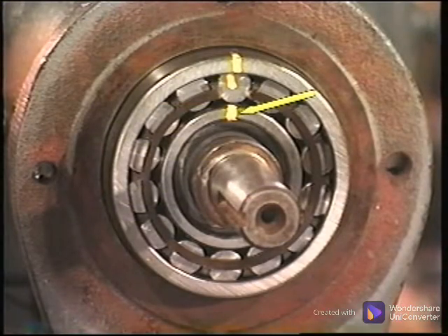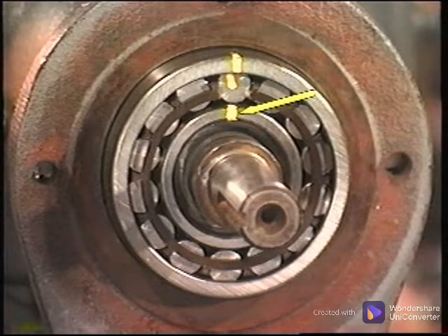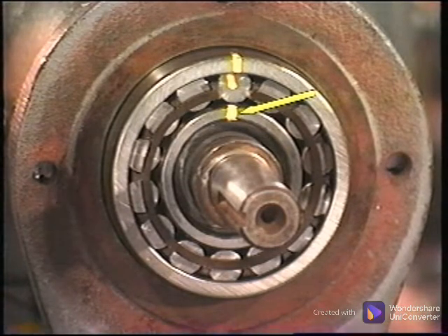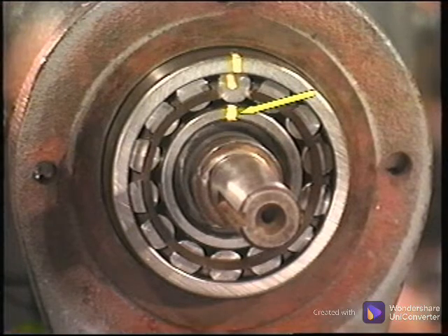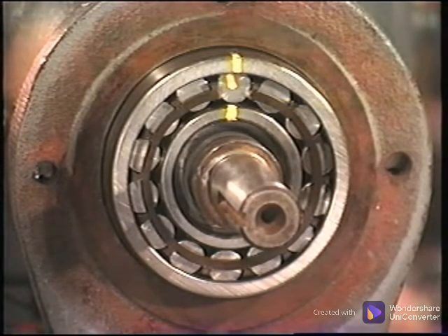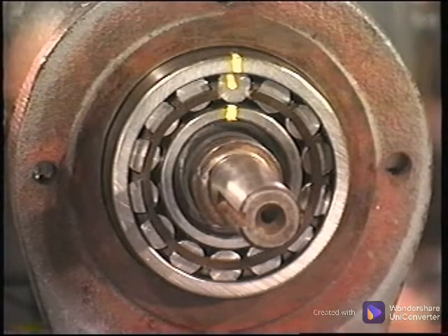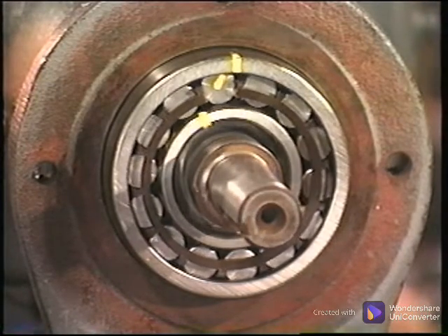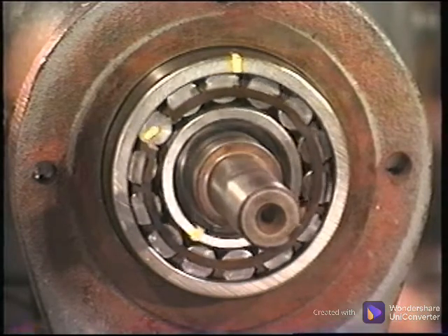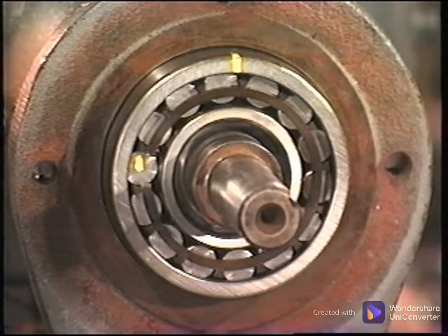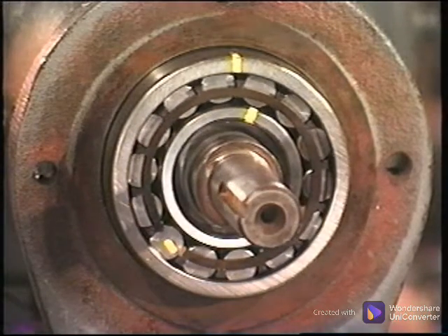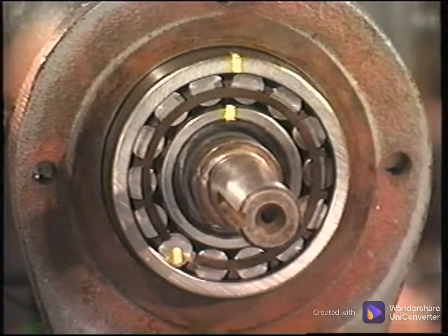We will focus on orders because that is a direct correlation to shaft speed. The inner race frequency can be approximated in the same way as the outer race frequency. With the reference marks lined up again, we will assume a defect at the mark on the inner race. As the shaft is turned, let's count the number of balls that pass through the inner race defect. 1, 2, 3, 4, 5, 6, 7, 8, and a fraction.